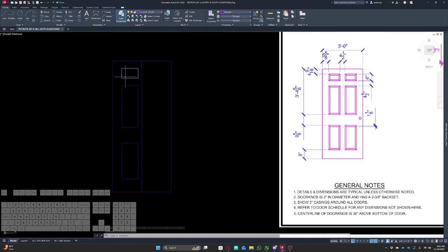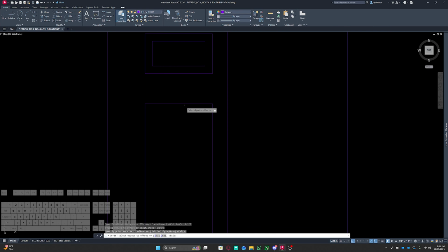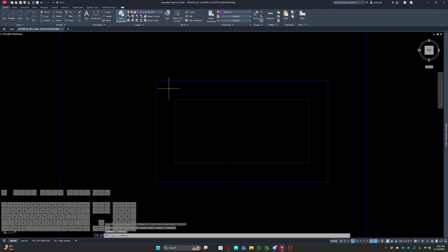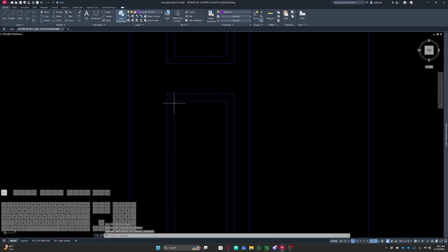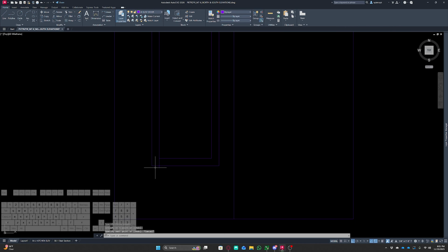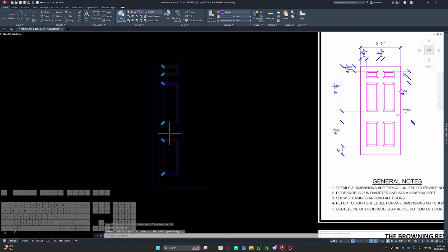I'm just going to move this back, so I'm leaving this right here. Next thing I'm going to do is offset by 1 1/8 of an inch. I will zoom in for these actually. Main reason we did rectangles is because I can just do the entire thing at once. I don't have to do any kind of funky trimming or anything like that. Grab my line tool and then just do each of these corners like so. I'm only going to do the left side because then I can just mirror it. Zoom out a tad and then grab all of those. Do a mirror command like so.